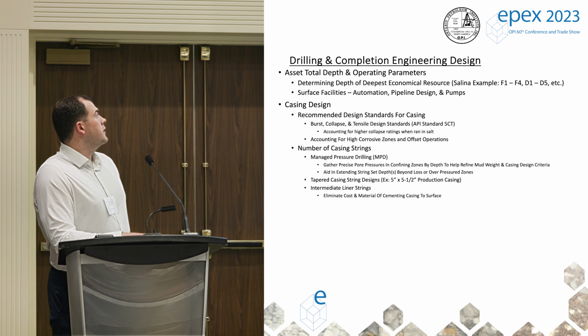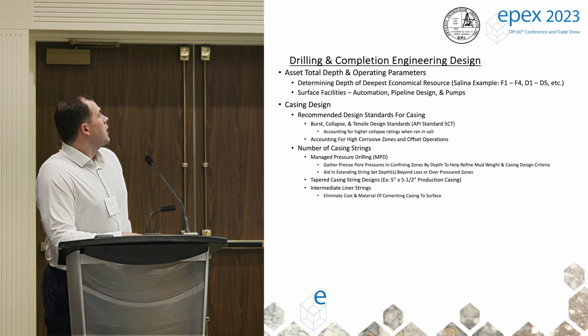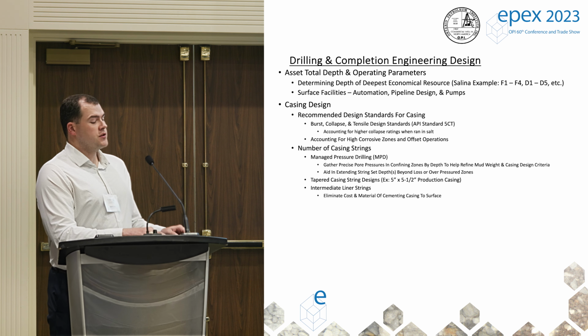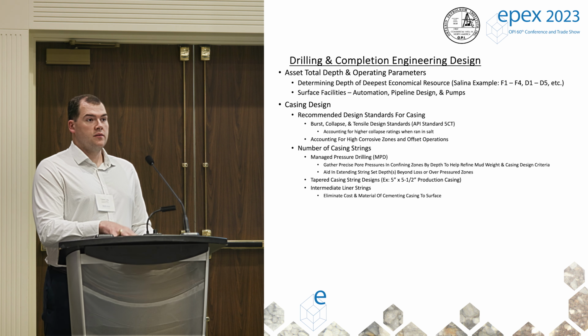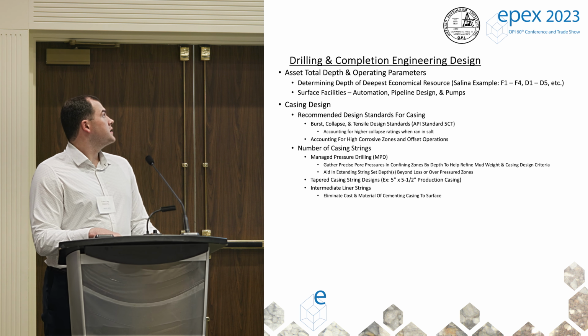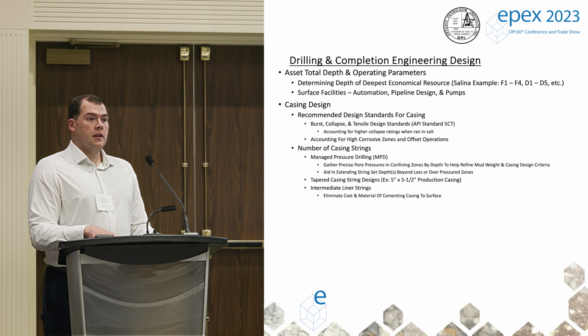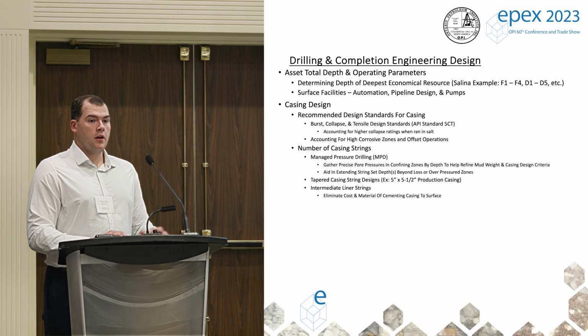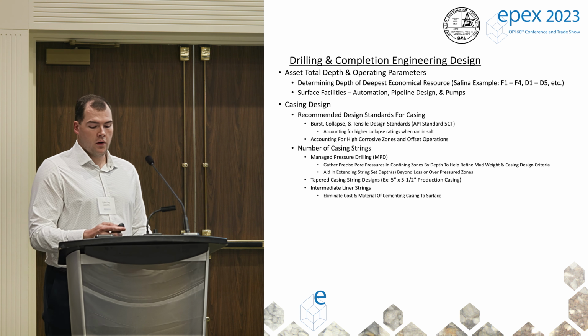That way you stay within your preferential rights. From there, once you gather all that data, for future wellhead and casing designs you start moving to cost savings where you have tapered strings, lowering your casing weights. You can start setting intermediate liners, reducing the number of strings you have to cement to surface, etc., and logging liability for open hole logs.